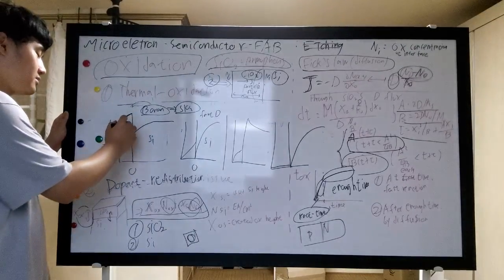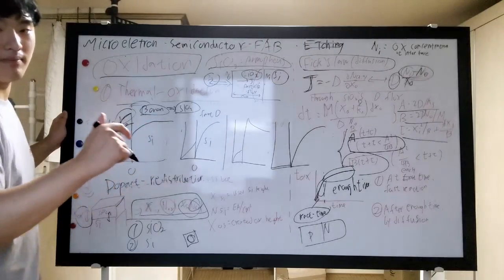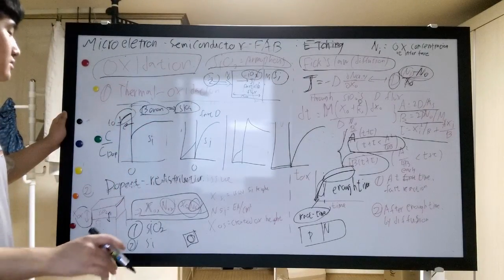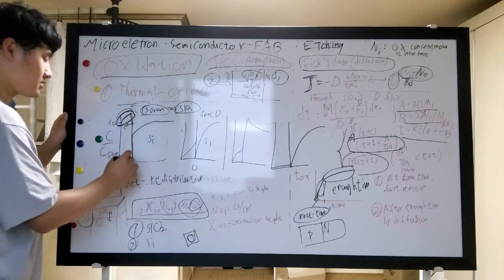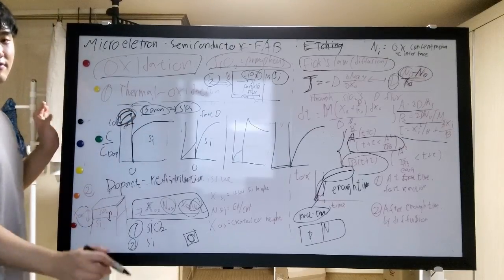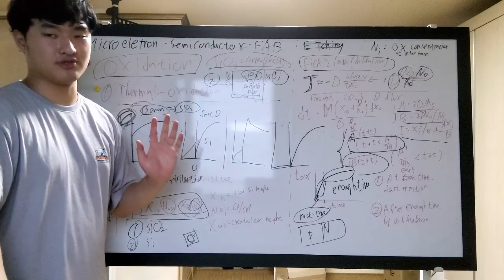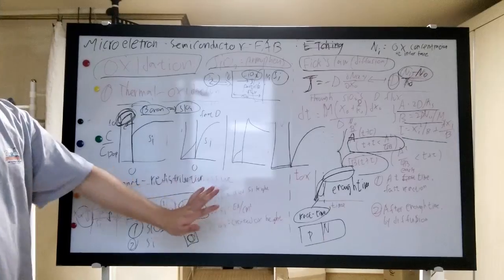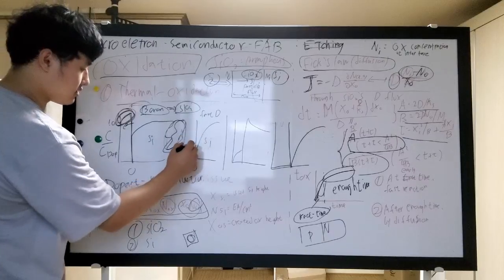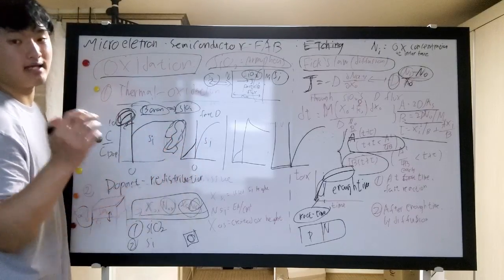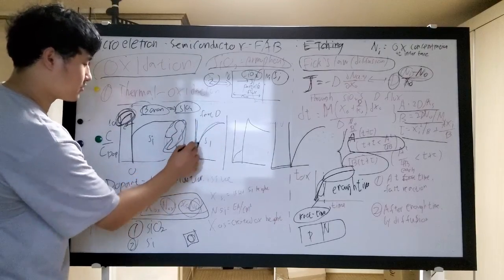For first, the dopant has moved to the silicon side at the interface, but with a low diffusion coefficient, then the concentration of the dopant will be concentrated at the silicon dioxide interface here. And if the diffusion was so strong, then the borons will move farther into the silicon's bulk, the deep body side. Just see here, there are some borons inside. But at the interface between the silicon and dioxide side, the boron will have strong depletion.